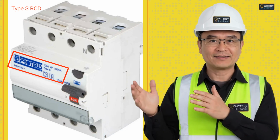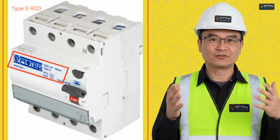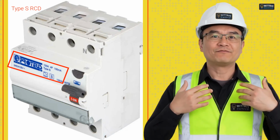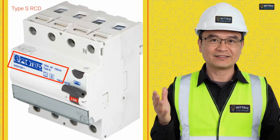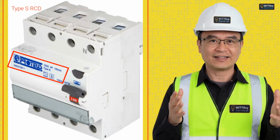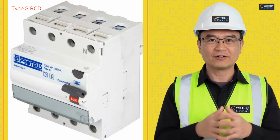I can see the type A symbol, so it can detect AC leakage and pulsating DC leakage. I can see 240, 415 VAC. That means it can be used on single phase or 3-phase AC supply, depending on the circuit connection. So this is a 4-pole type A, type S 100 milliamp, 100 amp RCD.